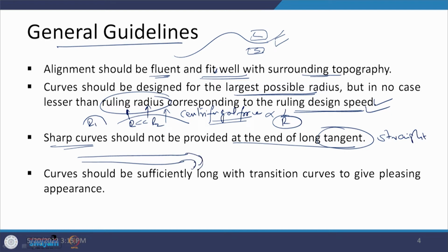Now, what is going to create a problem is that all of those vehicles which are moving here, all of these drivers, because of this alignment which is continuous and straight, are going to lose alertness. So, there is a reduction in alertness, and because of that they are more casual in their approach while driving, but all of a sudden if this type of sharp curve comes, then it may result in a hazardous or dangerous situation, and we have to take care of that.